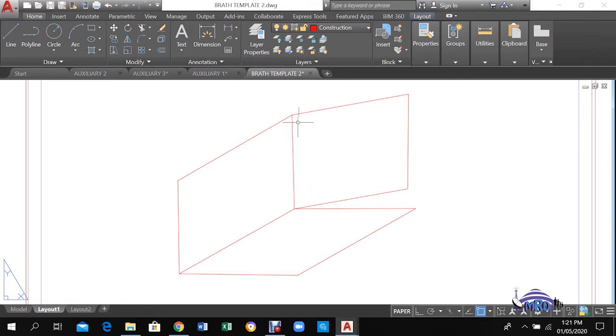Now, your end view would normally be at right angles to those two faces, and you would be able to produce the end view. But what you should note here in this representation is that this plane or this view is no longer at 90 degrees to both faces. Because this plane is now at an angle, what you would produce if you projected a view onto that plane would be slightly different to what you would see under normal circumstances. And that type of view projected on that different plane is referred to as an auxiliary view. You will understand a little bit more as we go along.